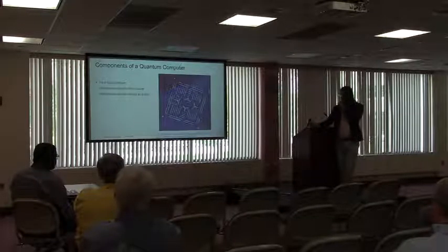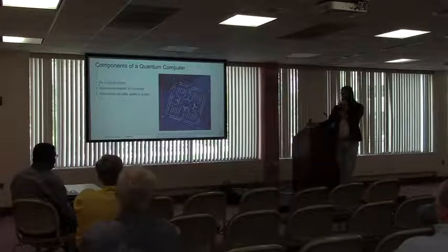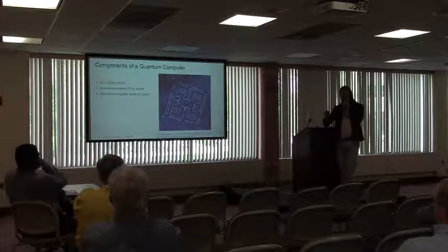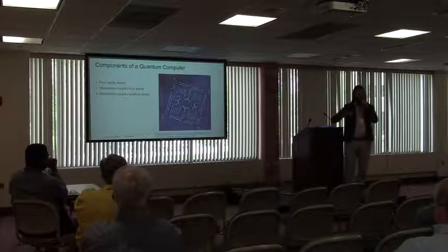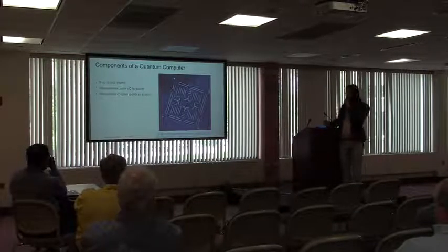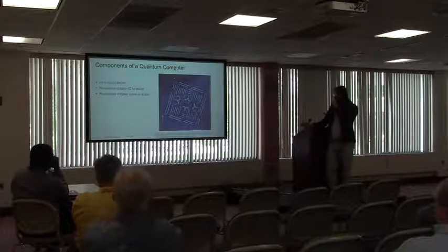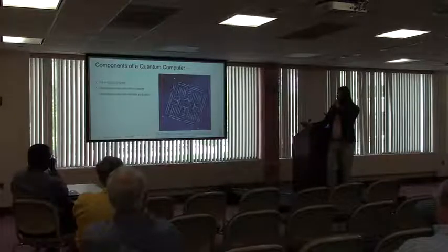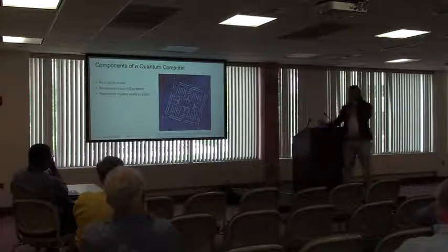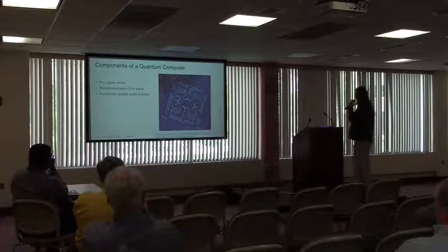And each qubit is also oscillating at a specific frequency, and you try to set the frequencies apart from each other so that they are not affected by the noise of each other. And then there are other resonators that couple it to the outside world. These can be your I/O ports where you introduce your signals and read them out.